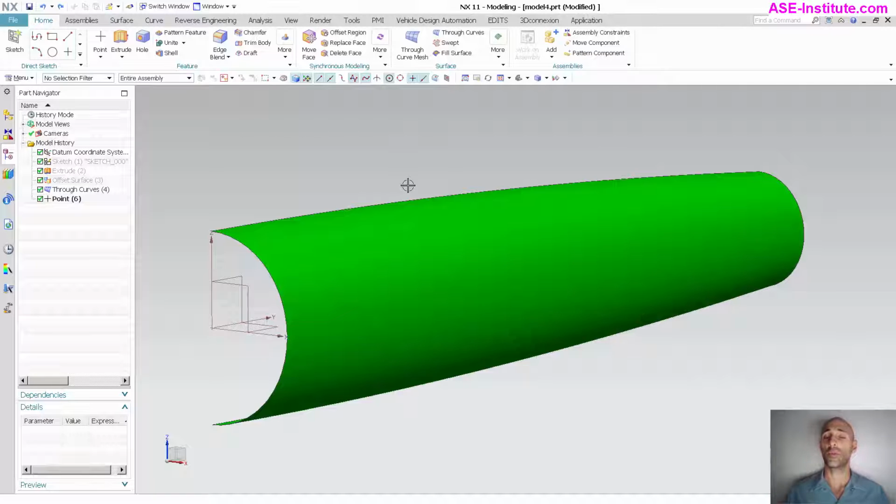Now, flat patterns are important for sheet metal parts, cloth parts, and when I say cloth parts, I mean composites, things that are going to be laid up with maybe fiberglass sheet or something really fancy where you've got Kevlar, or everyone's big on carbon fiber, that type of thing. So you don't want to waste any material, and you want to make sure that the cuts that you make are going to be correct. So you want to flatten the shape.